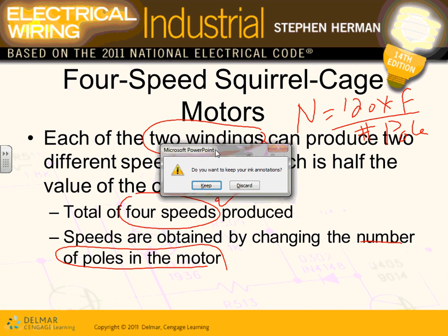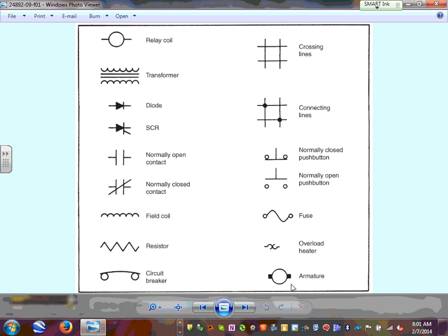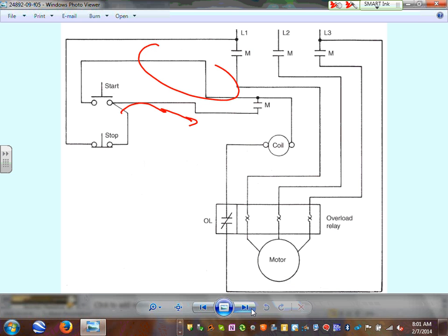Let me go directly to show you guys that one, speed control for that motor. Where am I here, Chad? Here you go. We talked about this one. Here's the spinning. Can you guys see here's my north and south spinning. So you have a magnetic field induced right into the rotor, and you have north and south poles next to it. What happens if you put north and north next to each other? They pull away from each other. That's the principle of operation of an induction motor. Spinning of the magnetic field will make the rotor spin.